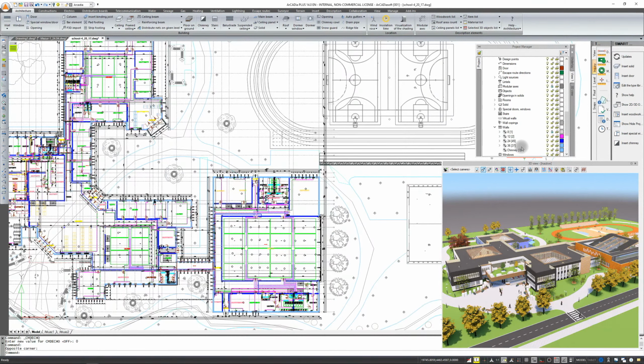Why is it done? To select the whole group with one click. To select a group, choose with the right mouse button, select elements, and you can then select all elements from a given group. You can enter the properties, you can change the whole group, not individual elements. I have a lot of walls here, so if I had to click them throughout the document, let's face it, it would not be convenient. So I select them all, and I can change, for example, font pens for descriptions, element properties, or even materials. Thanks to this division into groups, you can modify your projects faster.